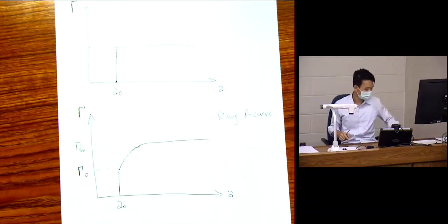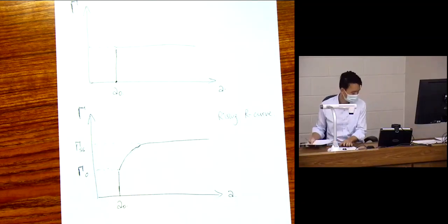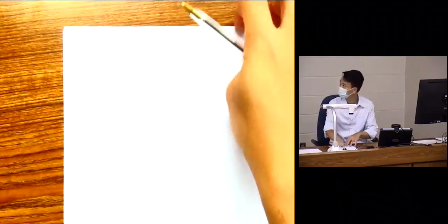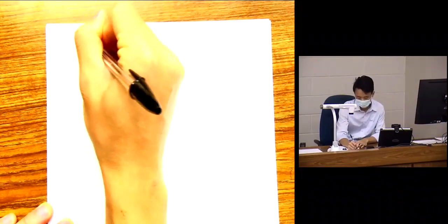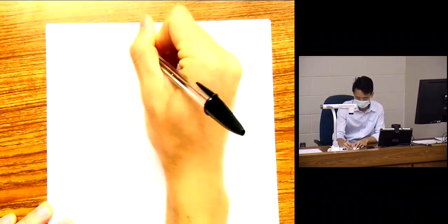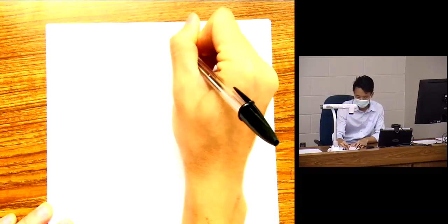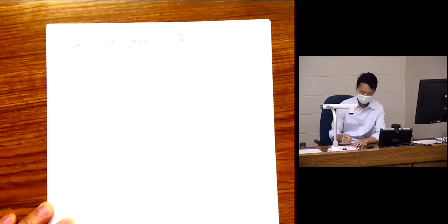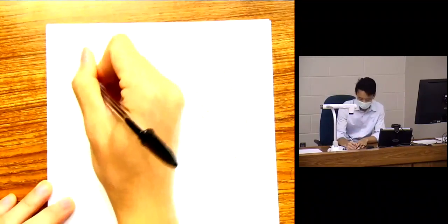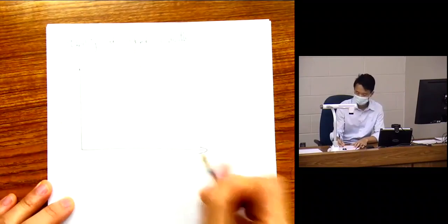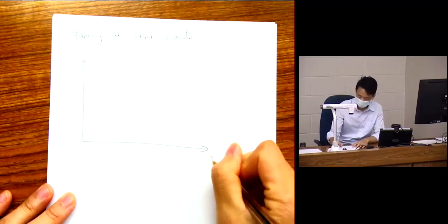So please just accept this for the moment, so we can go into how we use this to write down a criterion for stability, right? Because now we have all the ingredients for us to actually draw some conclusions. Stability of crack growth, right? So I'm almost done. Or stability criterion for crack growth. So what we need to do is just to put the resistance curve and the loading curve together on the same plot. Then it will give us a lot of insights.